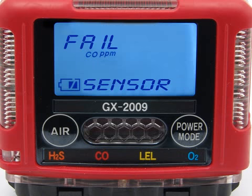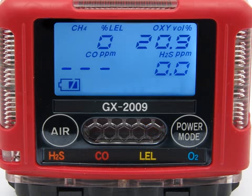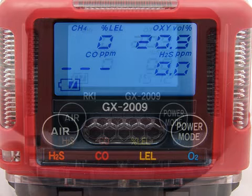If one or more of the sensors fail the fresh air adjustment, the display will indicate which sensor or sensors have failed. Press and release the power mode button to proceed to normal measuring mode. The gas reading for the failed sensor or sensors will be replaced by 3 dashes. Any sensors that fail the automatic fresh air adjustment should be replaced as soon as possible.